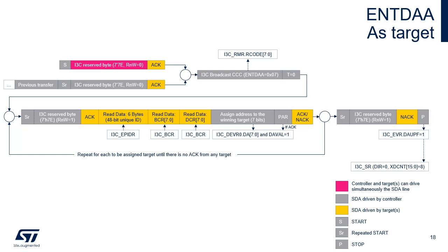Bits 47 to 33 of the 48-bit provisioned ID is the 15-bit STMicroelectronics MIPI ID 0x0104. Bit 32 of the 48-bit provisioned ID equals 0. Bits 31 to 16 of the provisioned ID equals 0. Bits 15 to 12 of the 48-bit provisioned ID equals the MIPI ID field of the I3C_EP_IDR register. This MIPI ID field is written by software to set and identify individually each instance of this I3C IP with a unique number on a single I3C bus.